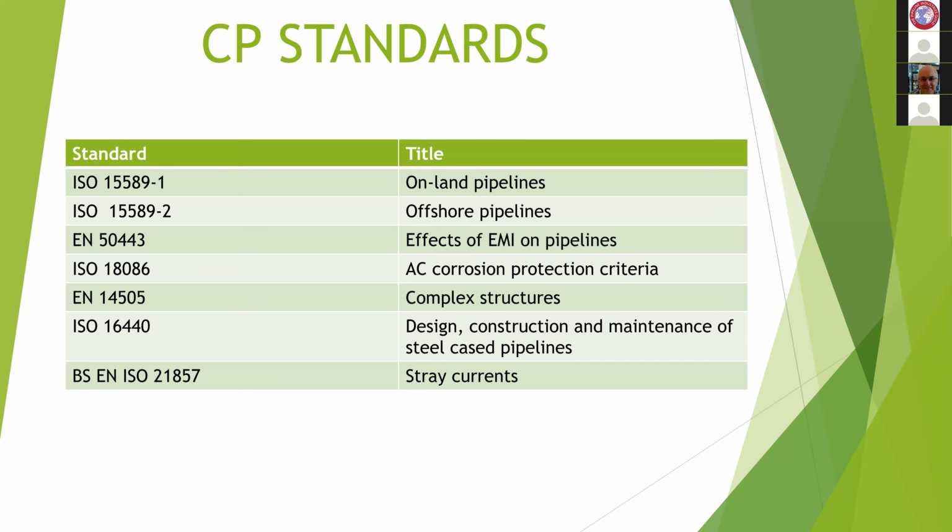I'll talk a little bit later about the spacers that we put on the pipes to keep them electrically isolated from the casing, and to keep them centralized in the casing. But they're very often poorly installed. And instead of being evenly spaced and separating the pipe, you end up with a whole collection of them at one end where they've pulled the pipe through.